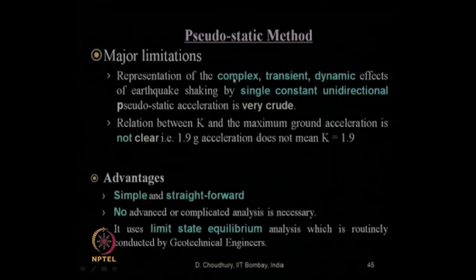It does not consider the complex nature of the dynamic load, it does not consider the time duration or transient nature of the dynamic load, and other dynamic effects like frequency of excitation, shear wave velocity, primary wave velocity, all these seismic waves which are traveling through the soil during earthquake shaking.